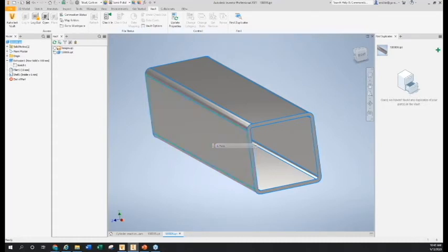And there's a couple of things to keep in mind. If you're using solid bodies, it does have to be one body or the same number of bodies, because sometimes with solid bodies, if you're using that for your modeling technique, you might have multiple bodies in the same part file. If there's two bodies versus one body, it's not going to think those are duplicates, just so you know.